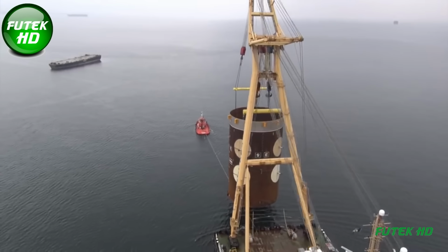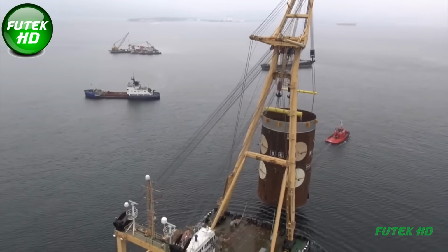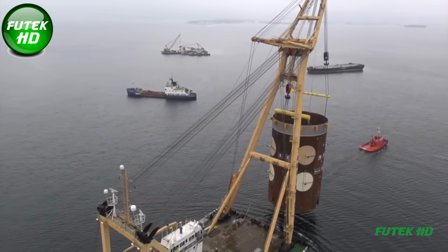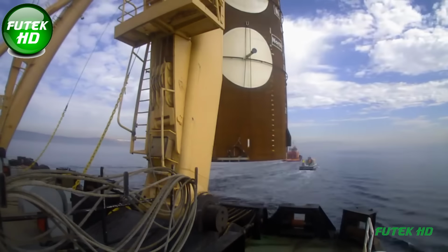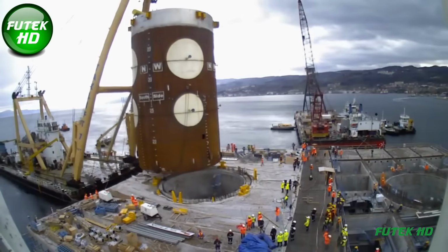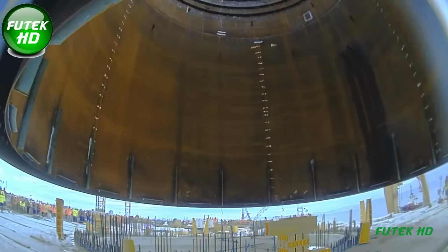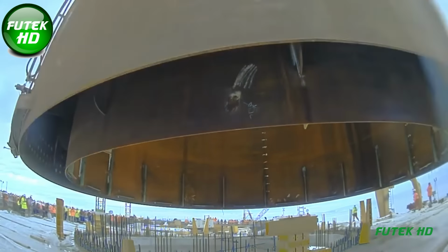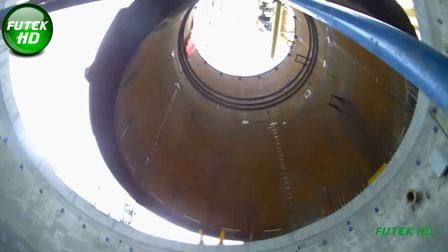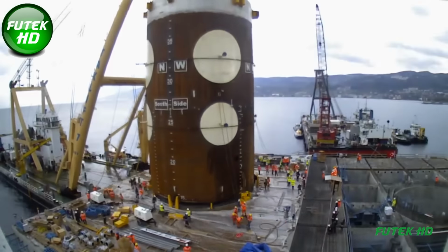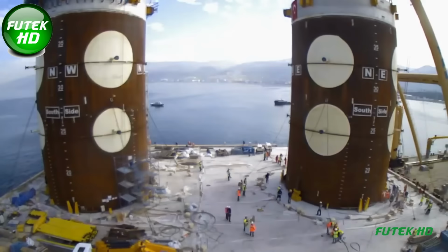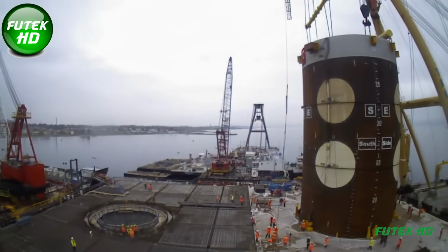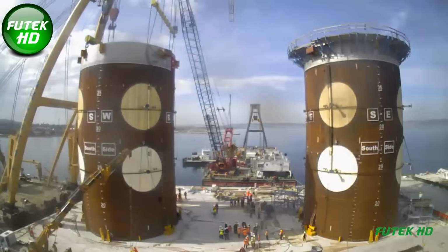Steel main towers, precision and speed. Suspension bridges traditionally use concrete towers. However, in order to accelerate construction, the Osmangazi Bridge adopted steel towers. By doing so, the construction timeline could overlap the manufacturing of steel blocks for the towers with the foundation work. The steel blocks were fabricated in Turkey's own steel factories, creating an efficient logistical flow. The assembly of these steel blocks took a dual approach.